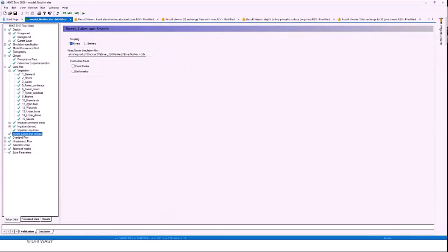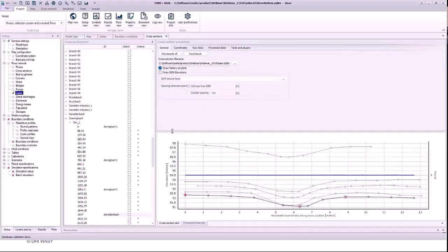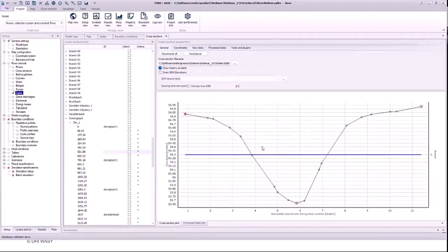Then you would couple it to a MIKE+ model. A MIKE+ model looks roughly like that. So we jump slightly into a different graphical user interface. And the river model is constructed by 1D polylines that define the branch. And for each branch, you can then apply cross sections. And this will basically define a simple 1D river model.